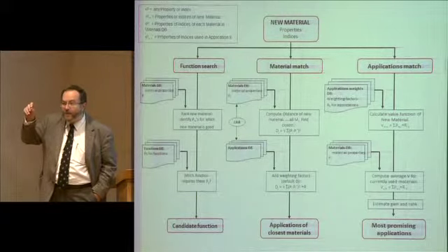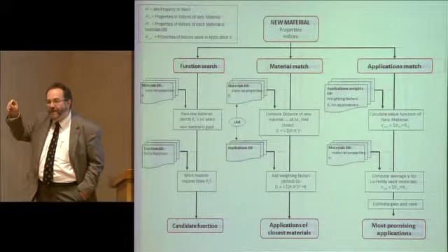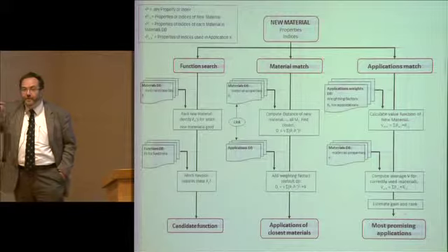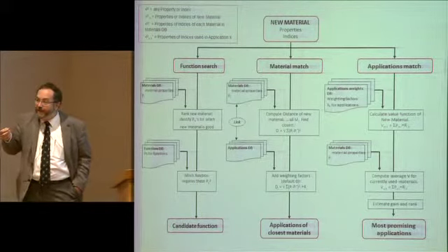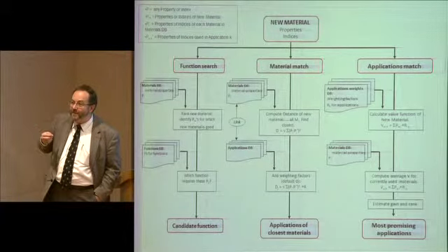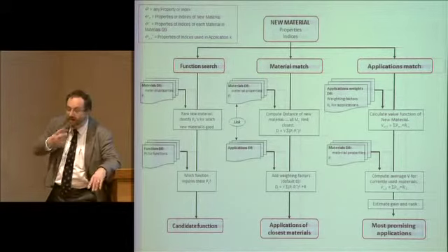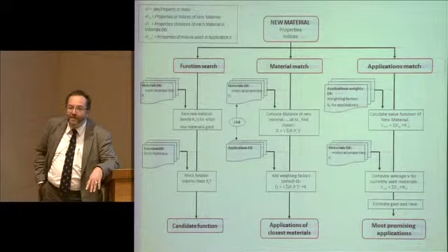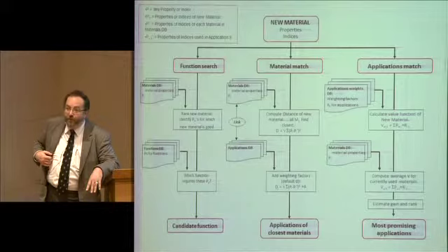The square of the modulus divided by elasticity limit shows how you can store a given property within a volume unit, meaning that this particular material might be interesting to make small springs, not necessarily low mass springs, but that sort of turns you towards a given application, where you can say that this amorphous alloy might be interesting to make springs.